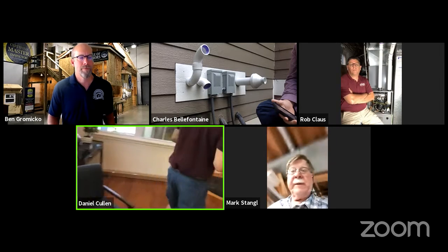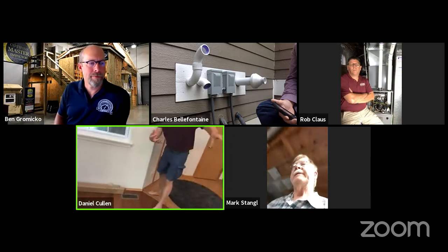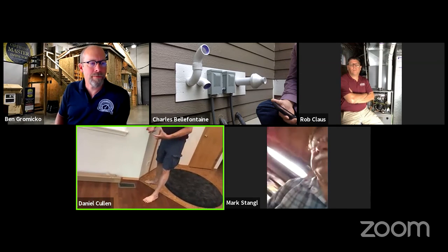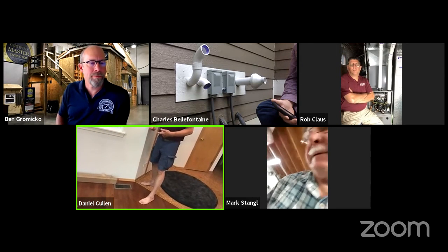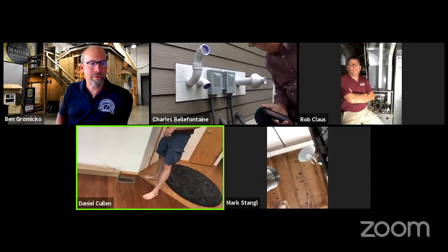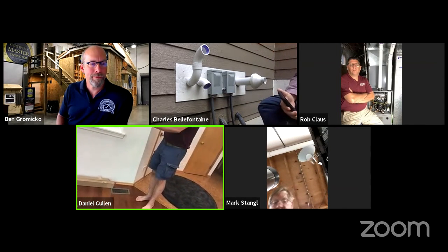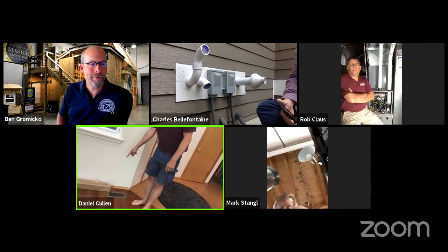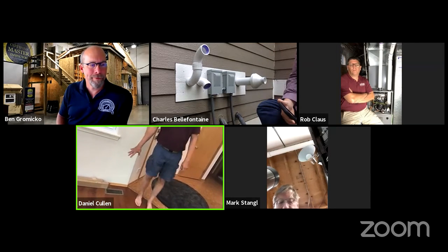moisture. So what I did in order to stop entraining air from the gravel layer below the slab whenever the unit was running was to use Great Stuff with a long metal tube and the trigger handle and seal all the register boots at the slab.